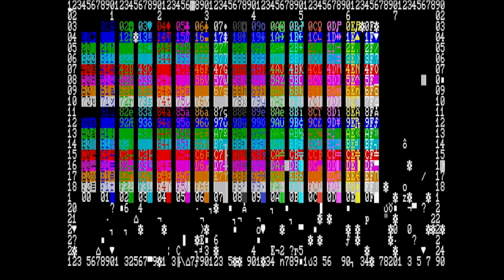Then we've got our blinking enabled. So this is the 40 by 25 mode. At the moment we haven't changed the clock timing to support the 40 by 25, but that's something we'll be doing later on in this video. So this is now showing the test pattern for the 4-color mode. This should be showing something along the lines of the background color and then the various combinations. So this is then a white background.